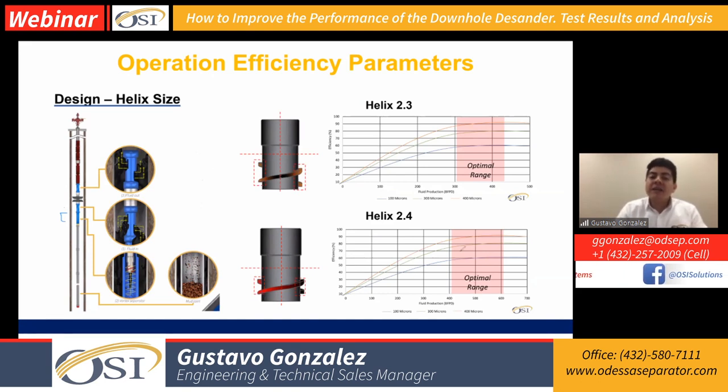If we're undersizing the helix and we're operating with a higher flow rate, now the linear acceleration generated in the system is going to force that centrifugal force to start at this point. So my drawdown is bigger, and what I'm going to do is cause that abrasion into the tailpipe. If that system is operating for just a couple of days, it's not going to cause any damage.